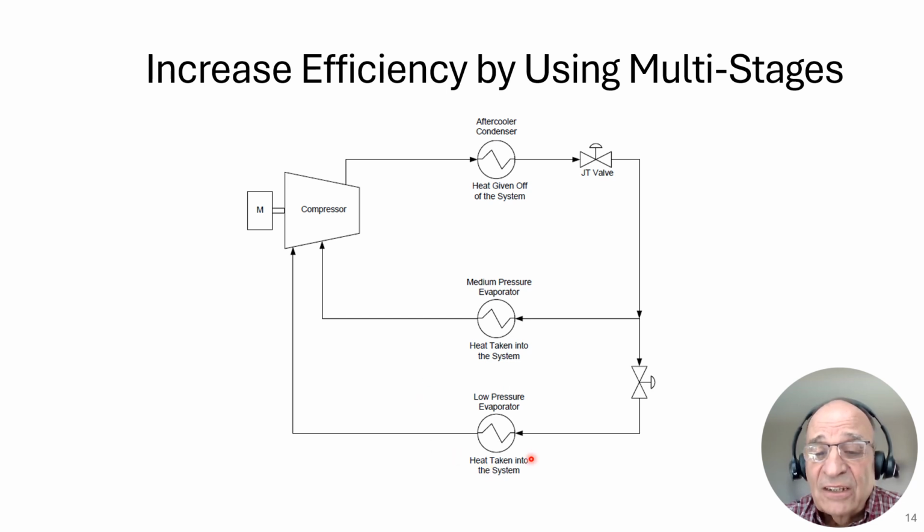Now, this process that I've shown here for making air conditioning and freezing with the same piece of equipment is also used if you have a constant stream of fluid that you want to cool down efficiently. If I had a fluid that I wanted to cool down to, let's say, 0 degrees Fahrenheit, and the fluid comes in at, let's say, 60 degrees Fahrenheit, well, it is ideal to first cool it down using this 35-degree Fahrenheit stream, and maybe you'll get the fluid down to 40 degrees, and then use this 0 degree Fahrenheit stream, and maybe you'll get the fluid down to 10 degrees.